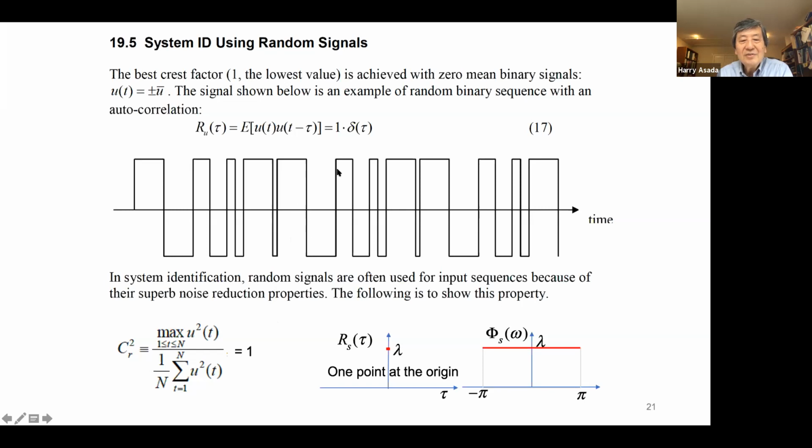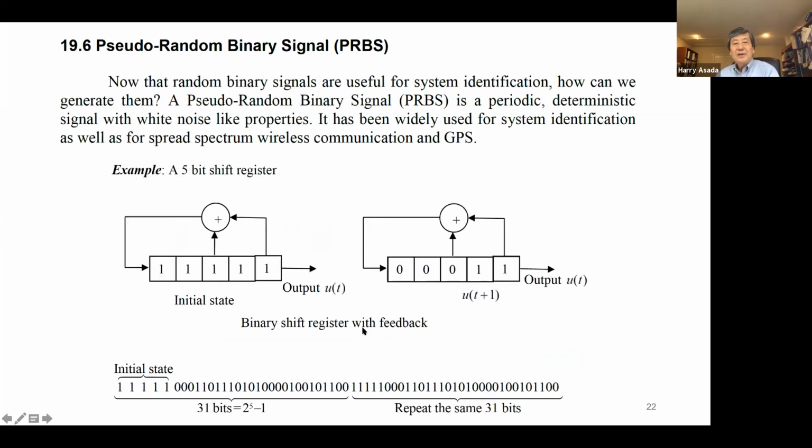You get a very large signal pumped into the system, and the system is sufficiently excited. With these conditions, it is white, uncorrelated signal. This random binary signal is, of course, to some extent an approximation. The pseudo random binary signal can be created quite easily. These days it is made in special chips, but it is produced with a very simple logic, basically using a shift register.